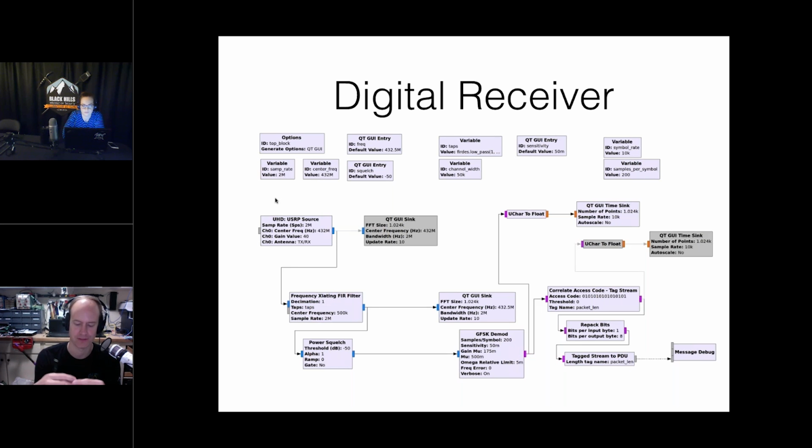I don't know if you remember, this is the most physics I'm going to get into, but if you remember the inverse square law, that just means that if a signal is emanating in all directions, you start to lose power, not linearly as you go further away, but much faster than that. And so it's much easier for me to jam something 1 meter away than 10 meters away. Vastly easier. So you can use the HackRF without any external amplifiers to jam things like the car key fob, which is kind of a nice starter project for a lot of folks.